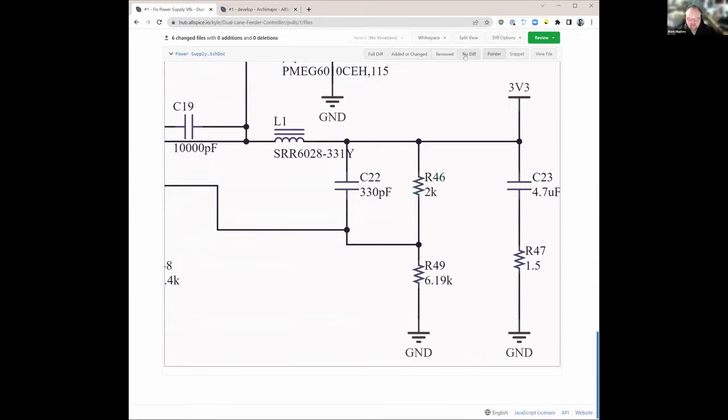All right, so it was sitting on top of it. So it was a 10K before and it's a 2K now. Yep. So previously 10K, on a 3.3 volt net, we're going from a 2-volt feedback voltage down to like a 0.8-volt feedback voltage. So yeah, somebody just picked the wrong resistor. It happens.